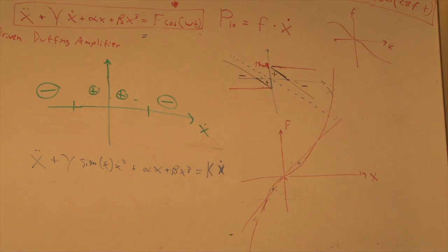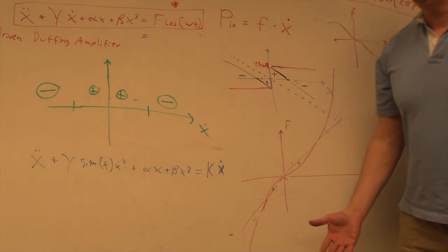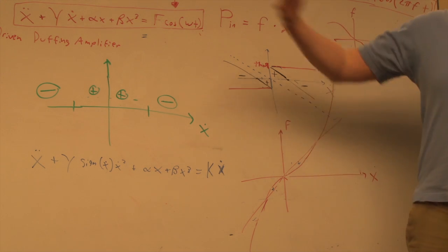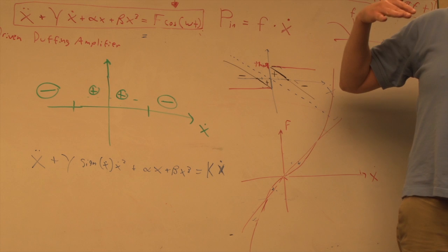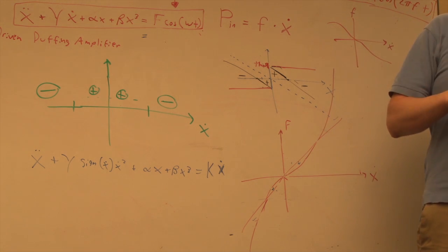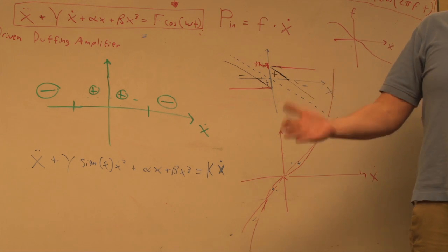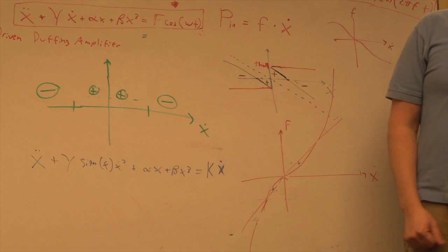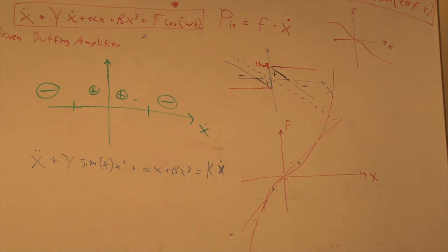So as long as it gets farther away from the origin, at some point that would be your steady state amplitude. Yeah. So as long as the natural damping takes out more energy as you get higher velocity than what you're putting in, and as long as you're putting in more than the natural damping's taking out below that velocity, then you can get resonance. And the way we've been saying that is damping has to be higher order than the driving to achieve a stable oscillation. Right.